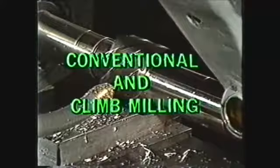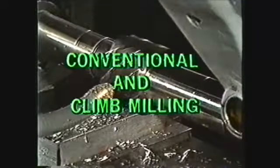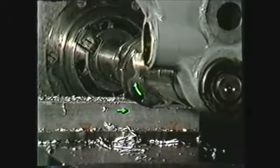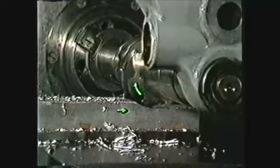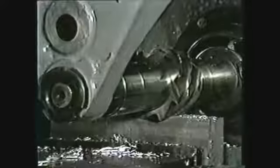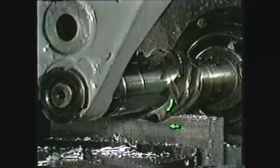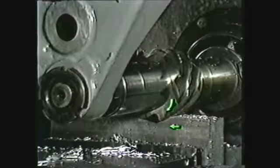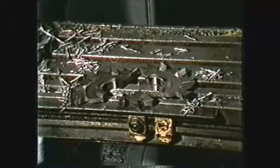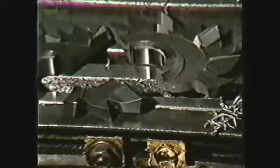The two methods of machining using a plane milling cutter are the conventional milling method and the climb milling method. In conventional milling, sometimes called up milling, the work is fed into the rotating direction of the cutter. This gives the appearance of the work being lifted at the cutting point. In climb milling or down milling, the work is fed with the rotating direction of the cutter, which tends to force the work down into the vise at the cutting point. The problem which may occur with climb milling is that machines not equipped with a backlash device may pull the work into the cutter and cause cutter breakage.